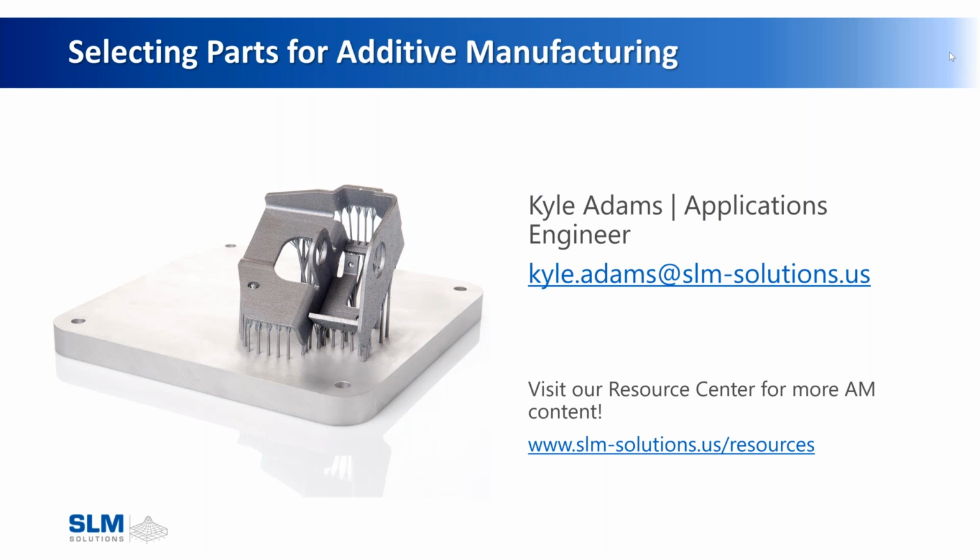For the FDM process, the extrusion head is what's laying down your material, and it's only laying down material where you want it. So it will extrude out of a head, and that's more of a direct deposition, where powder bed lays down a wide bed and then lasers where we want the part to be built.